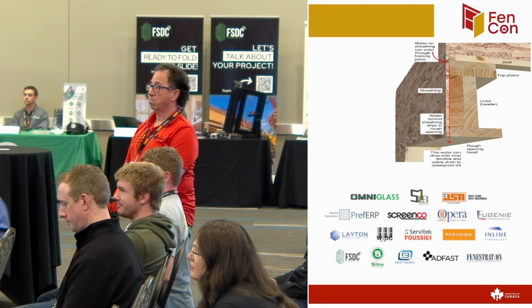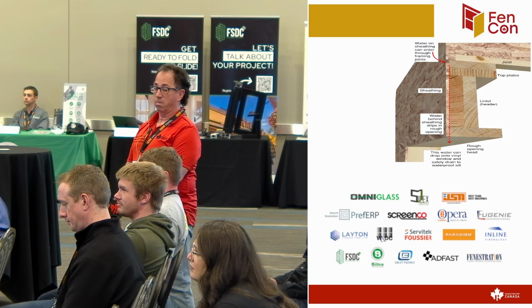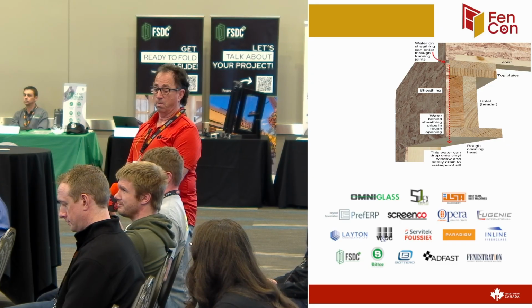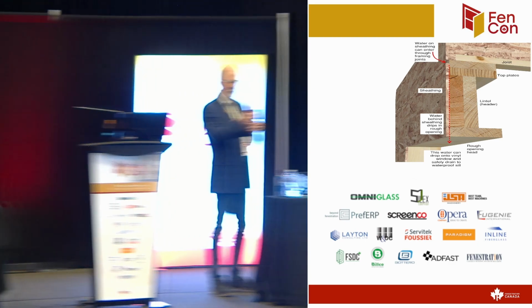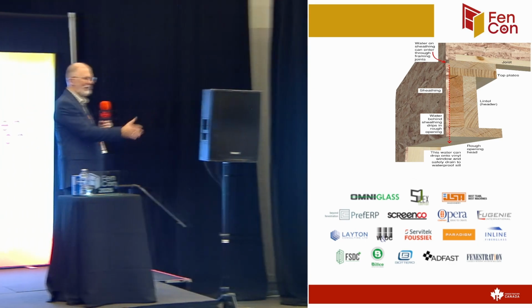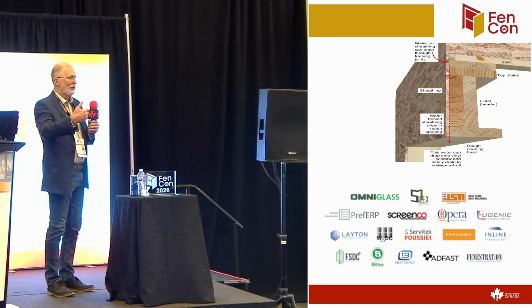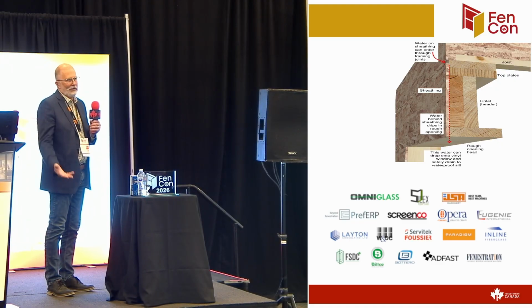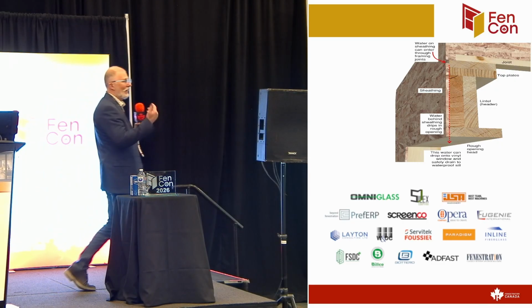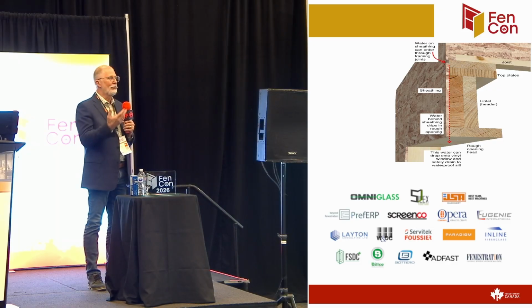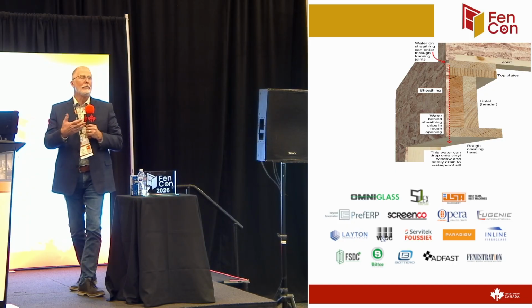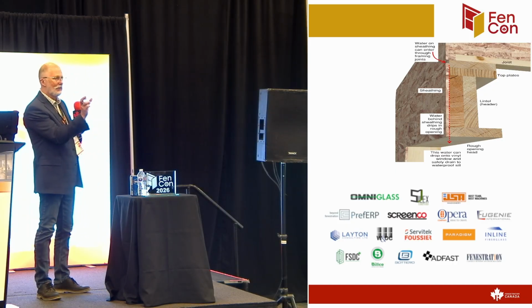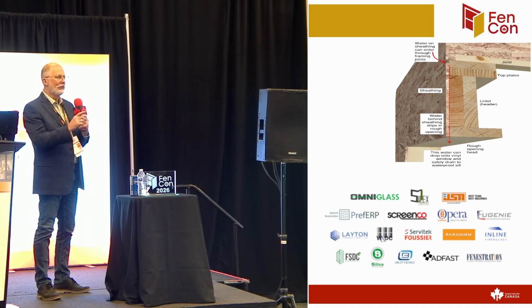Exactly. So have you built any net zero or passive house buildings? I bought one. Okay. So what do you buy off the shelf to finish from the face of the window to the outside of that ledge when you set the window in? You have to custom make something. I think that's the biggest risk. Any of the net zero or passive house work we've done, we couldn't find an off-the-shelf product. There are a couple of window manufacturers that have attachments that can be fastened to the front of the window, but generally they're not big enough in that application.